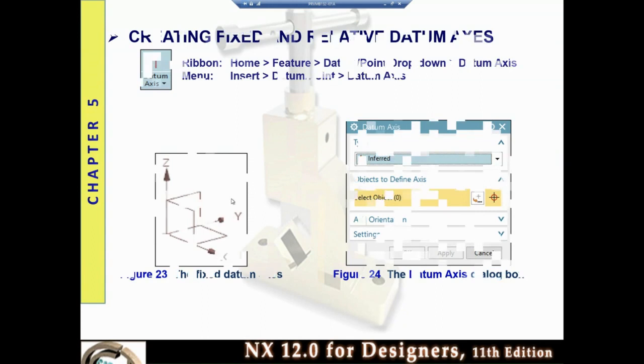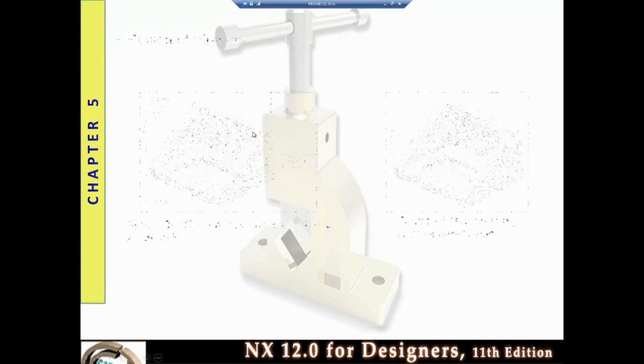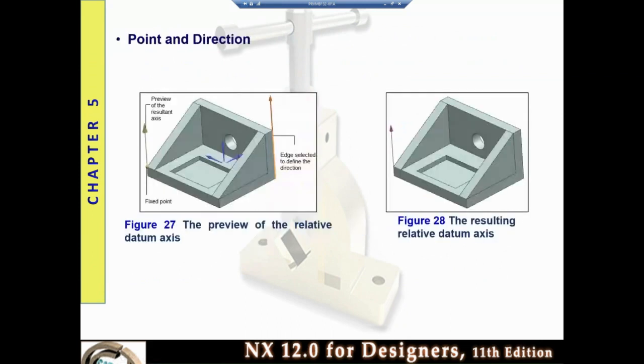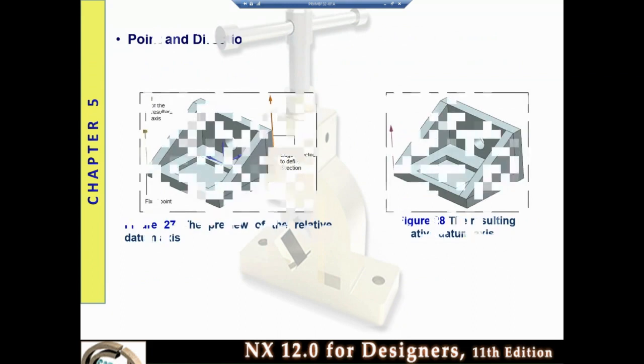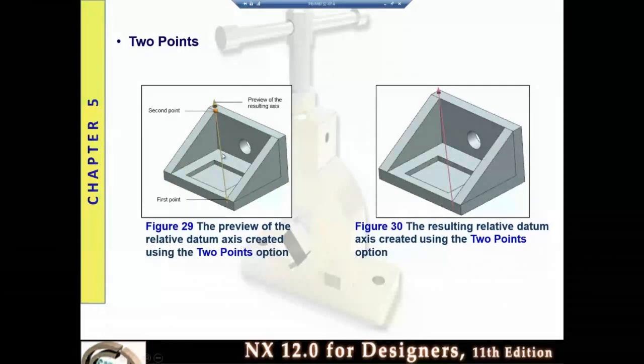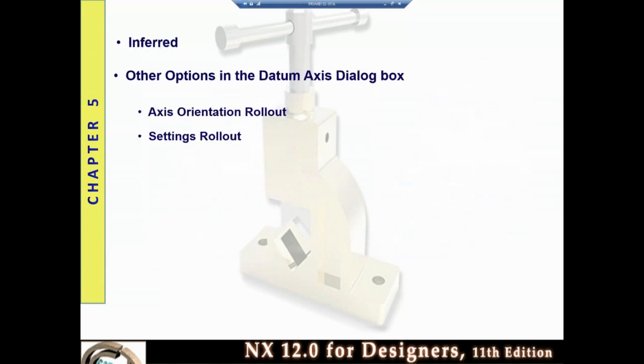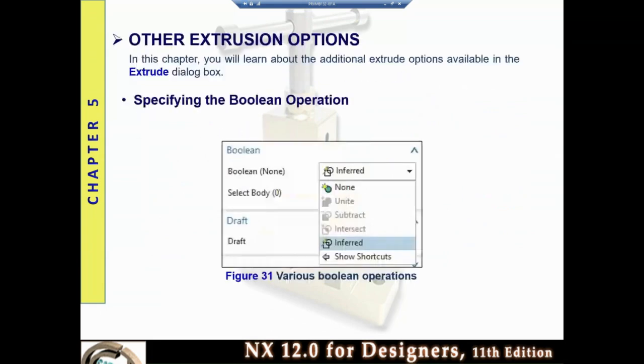And also the same thing for the axis. You would be able to create the axis the same as what we created for planes. We would be able to create it on a curve. So all of these are exactly like each other. If you know how we can create a plane, it's exactly the same thing for the axis. You can create an axis there by connecting 2 points, so technically you will have an axis. The axis will help you once you're using, for instance, revolve, because revolve would rotate around that axis.